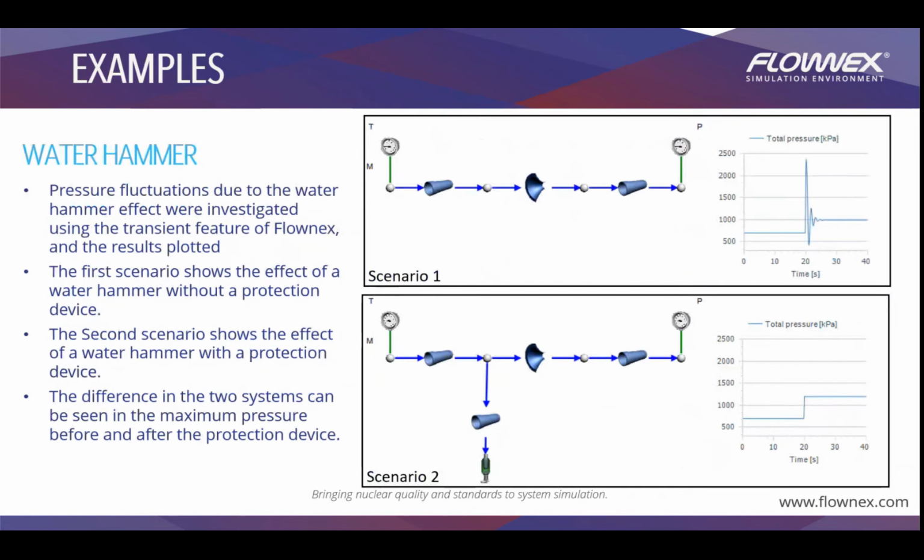Most of the water distribution systems are done over elevation, or they have a height difference. So we have head, and that means that there will be somewhere in the system where water hammer will be generated if a pump shuts down or a valve suddenly closes. Then we'll experience a water hammer. Water hammer simply means that it is caused by the water coming back, which causes pressure spikes in the pipeline that can burst the pipelines, causing a massive problem in the system itself.